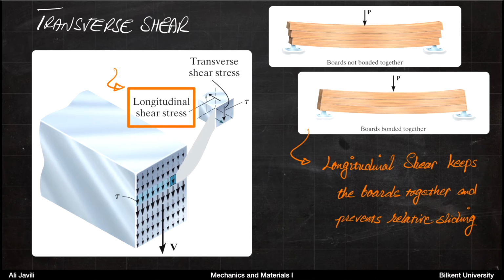All right, so I think this example explains very well that if you have a problem like this, our simple problem that we talked about, you have a beam, you apply a force, you develop a shear stress. Not only do you develop a transverse shear, but you also develop a longitudinal shear stress. And then what we want to do next is to calculate the longitudinal shear stress, and then because they are equal, that would also give us the distribution of the transverse shear stress itself.